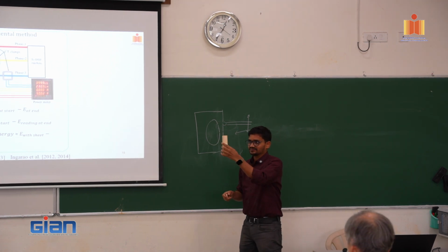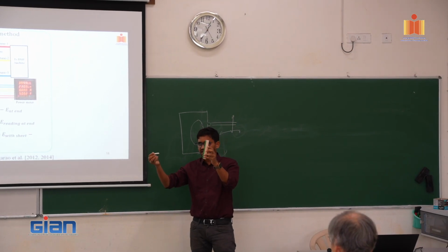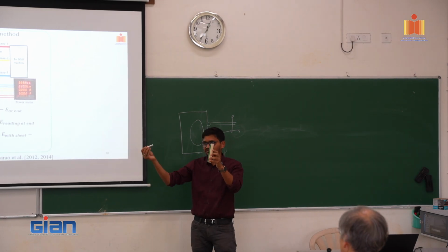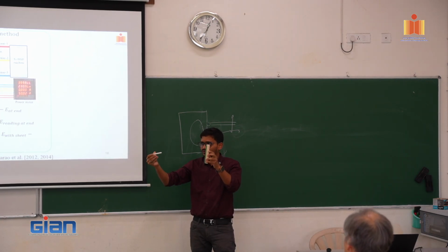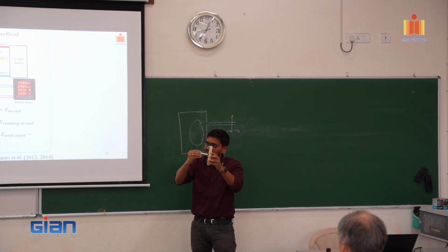Let's say this is the plate, and this is the tool that you are trying to deform with. If the tool is moving without engaging with the workpiece, that is the energy of the free traverse. Now the tool comes and engages with the workpiece. It is giving a force that will cause a plastic deformation, and it's still moving.